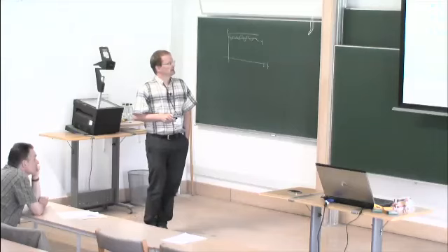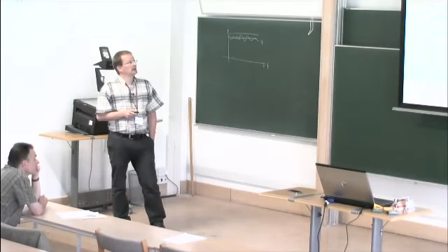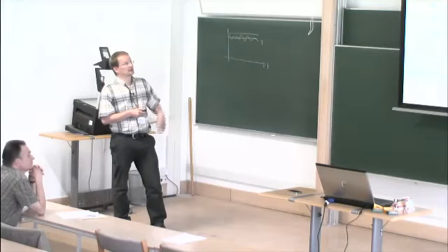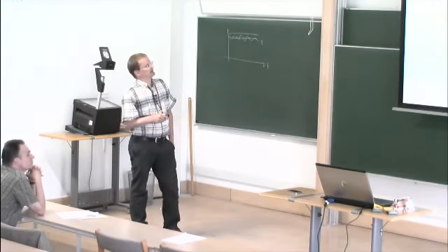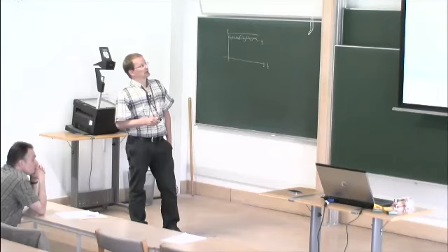It corresponds to an input which is an AR1 process with a pole at the inverse of the zero of interest. And if I use that particular input, I get the same accuracy of my estimate of the zero, no matter what the order is here, and no matter what the order of the true model is, as long as it's larger than n naught. So here is just a graph. First, here I estimate two zeros inside the unit circle, and if I go from model order 3 to 5, you see that my Monte Carlo realizations spread out much more than here.